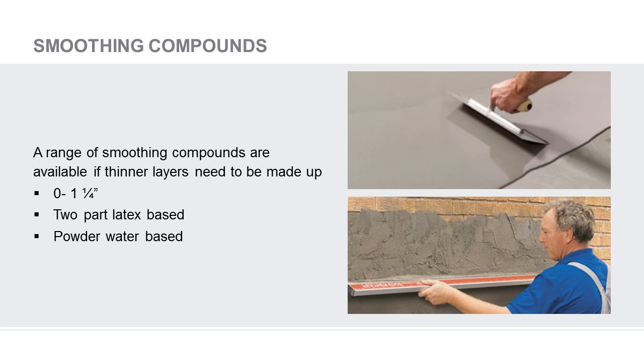As you need a flat base to tile on, smoothing compounds are ideal. Cost-effective way to achieve this: tile mortar should not be used to prepare surfaces greater than a 1/4 inch thick. Use an appropriate substrate repair mortar or leveling product for that application. Commonly, there are two types: latex and powder, or a pre-blended polymer modified patching or self-leveling compound.